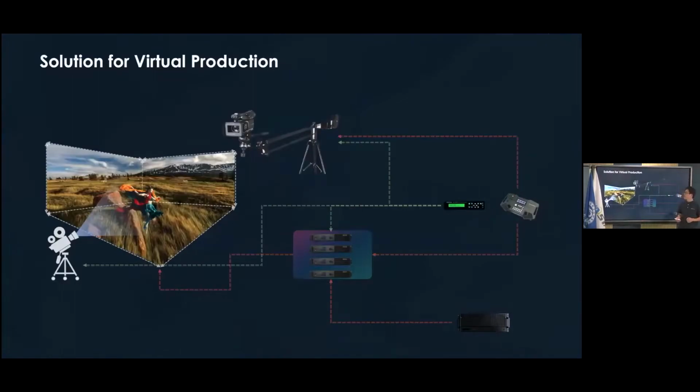So this is the frame multiplexing. Now let's come back to the whole solution for virtual production. As you can see, from the video source inputs, we support the HDR10 444 format, and PQ modes will also be supported. And from the camera side, to cooperate with the controller, we have the shutter phase and Genlock phase offset to help get rid of the scan line problems and also the black field problem.